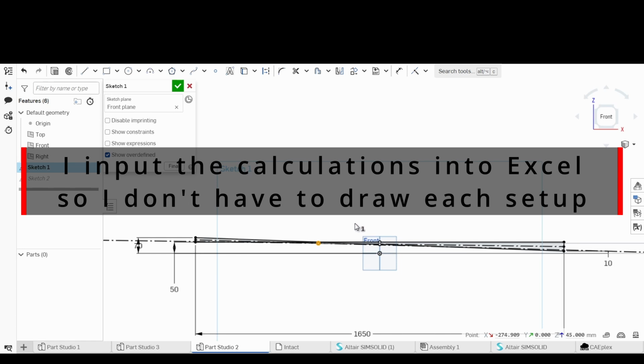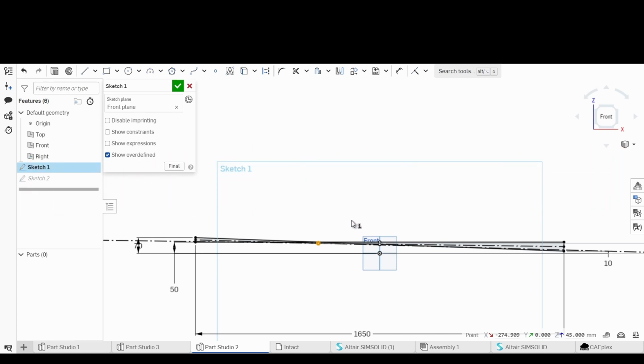So I did that for different instant center locations and the different lateral G's. So basically, I'm just finding the roll point from static to 0.5 G, and then from 0.5 G to 1 G, and then the difference between the 1 G and 1.5 G. So it's just showing the roll location from one scenario to the next.